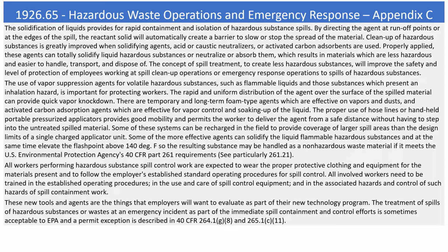Cleanup of hazardous substances is greatly improved when solidifying agents, acid or caustic neutralizers, or activated carbon adsorbents are used. Properly applied, these agents can totally solidify liquid hazardous substances or neutralize or absorb them, which results in materials which are less hazardous and easier to handle, transport, and dispose of. The concept of spill treatment, to create less hazardous substances, will improve the safety and level of protection of employees working at spill cleanup operations or emergency response operations to spills of hazardous substances.